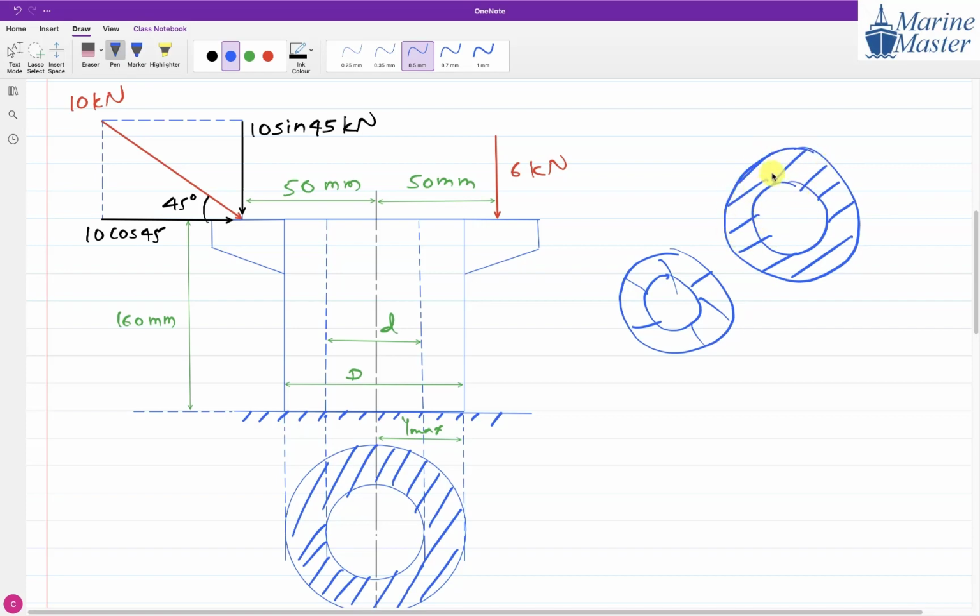And generally we prefer an angle of 45 degrees, guys. Don't show the hatching like this, this is the wrong way. This is the correct way, everyone. Whenever we want to show the hatching, only one direction, guys.